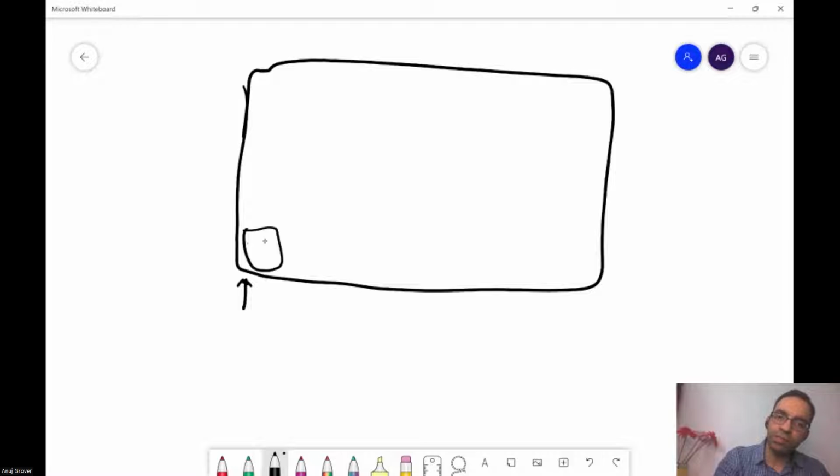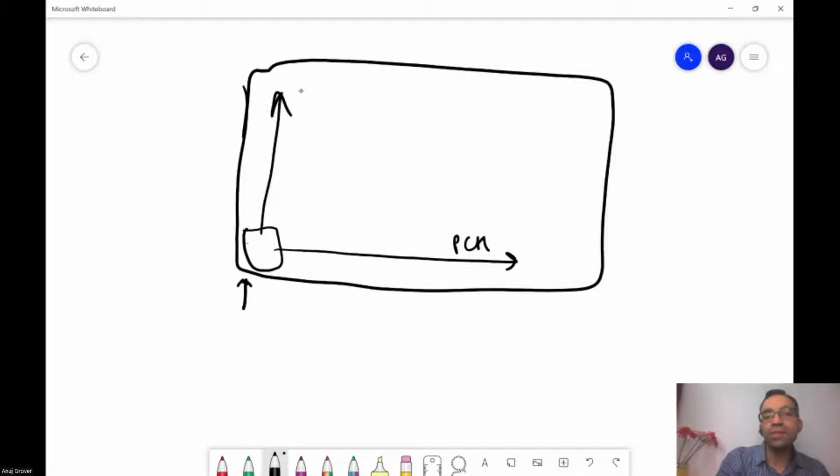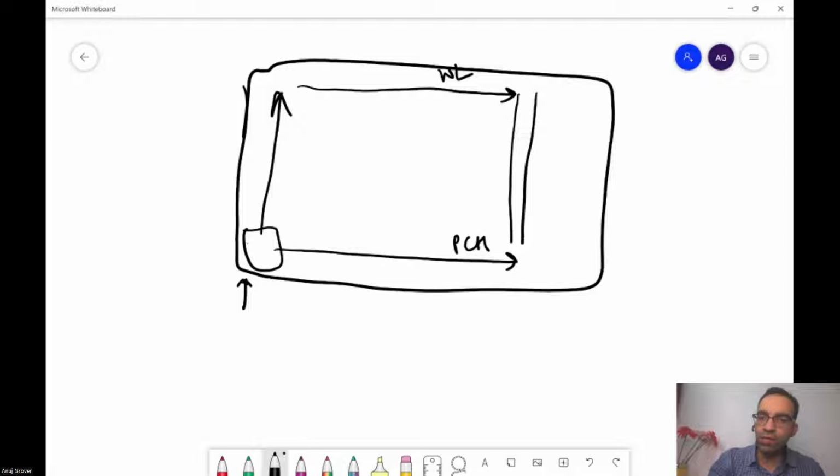It goes to the clock generator here. One clock goes to the pre-decoder. Another clock goes to the IO region and turns off pre-charge. This results in generation of the word line. Then this word line leads to generation of a differential on the bit line pair. You want another signal, SAEN, to come and trigger the sense amplifier only after sufficient differential has been created. Is the problem statement clear?